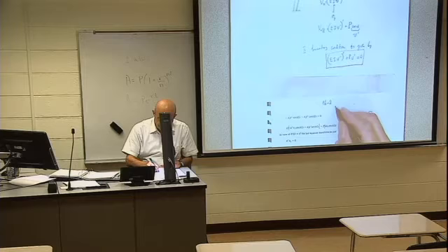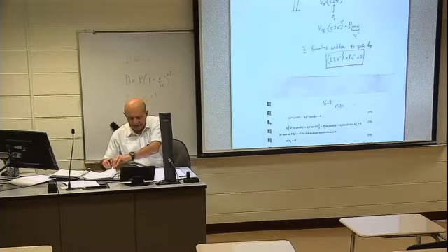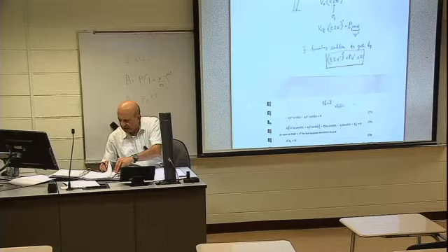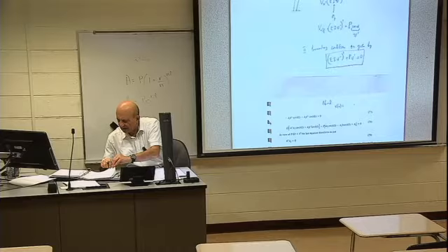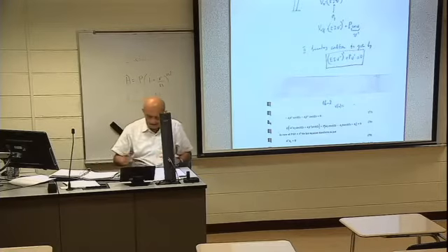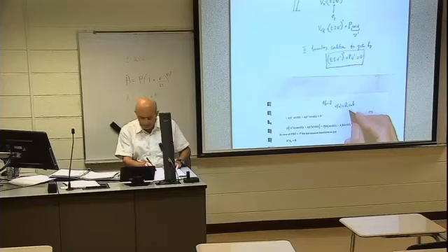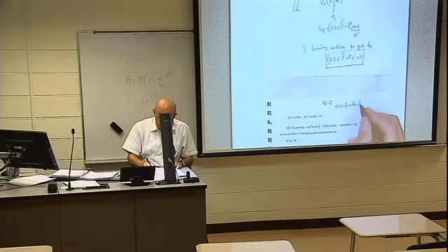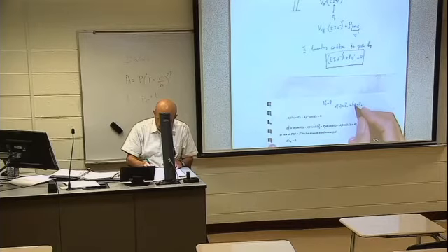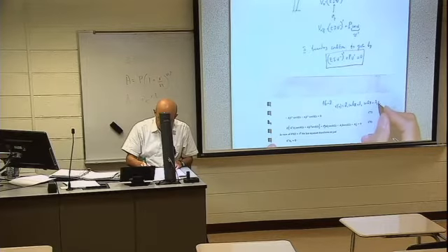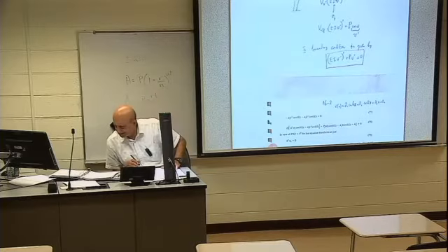We have V of x equals, let me see what expression, the general expression that we have is A1 sine kx plus A2 cosine kx plus A3x plus A4. And that is on page 15.5.